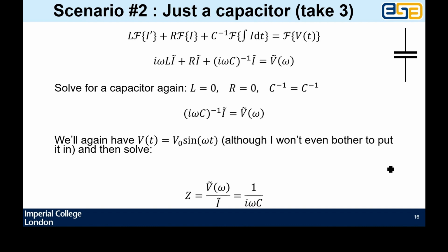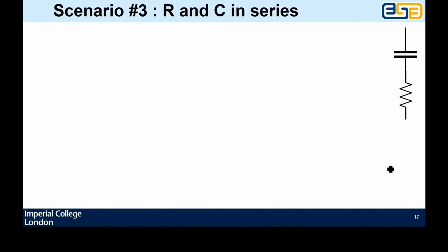So clearly, you can just rearrange the penultimate equation on that slide to be the bottom equation. So I've just divided both sides by I tilde, and I get left with the correct expression for the impedance. So we are going to use this current formulation from now on as the way of describing this system. So we'll get rid of Q, which we were helping to understand how it looks a bit like a spring mass damper or a water wheel, and we're going to stick with current I. Okay.